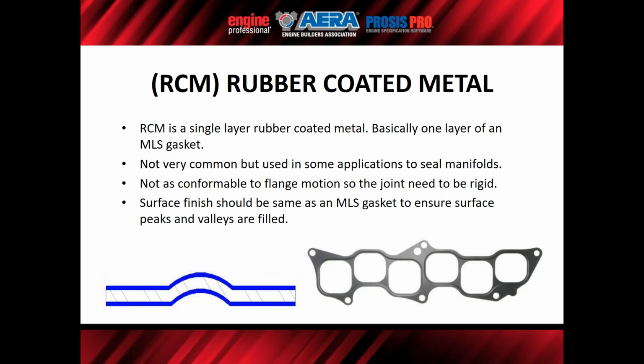But you have choices. Again, some of these RCM gaskets have thicker rubber coatings. This blue represents that coating, so that coating could be anywhere from 1 to say 15 thousandths thick. The thicker the coating, the rougher the surface finish you can tolerate. So you can do that.